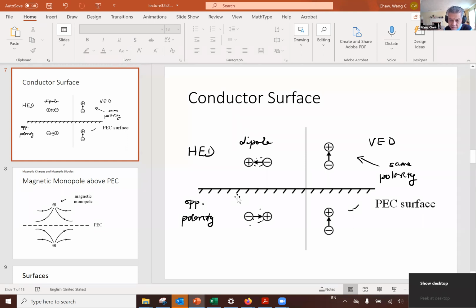If you have a conductor that is imperfect, then in the static case, the electric field will still be completely shielded out. But if this is time varying, if this dipole becomes a horizontal dipole where the currents go back and forth, then as we said before, the electromagnetic field is not zero below anymore. So this image theory does not apply. It only applies to the electrostatic case.